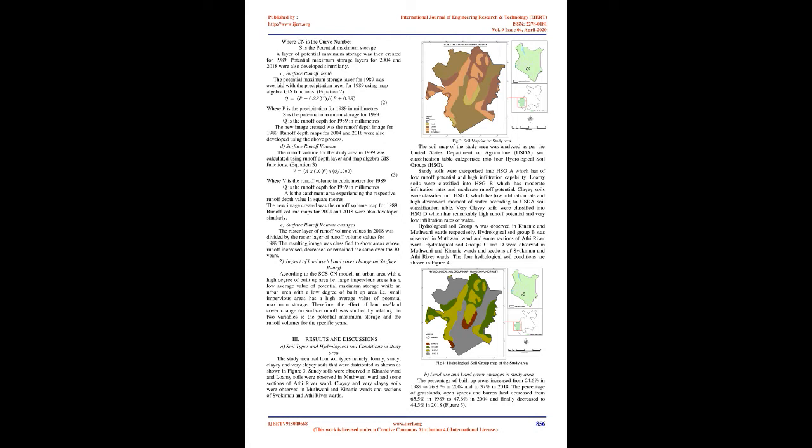1. Soil Conservation Service Curve Number, SCS-CN, Method. A. Curve Number. The land use / land cover image for 1989 was overlaid with the HSG map for 1989 and then recoded, and curve number values calibrated using the SCS table, USDA 1972. From the above process, a curve number image for 1989 was created. Curve number maps for 2004 and 2018 were also developed using the above process.